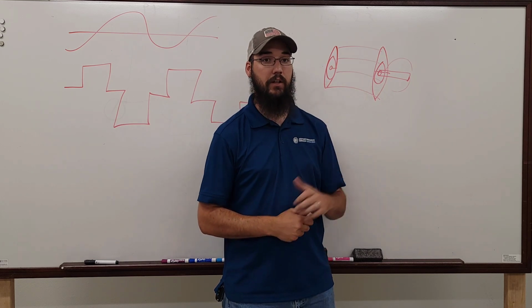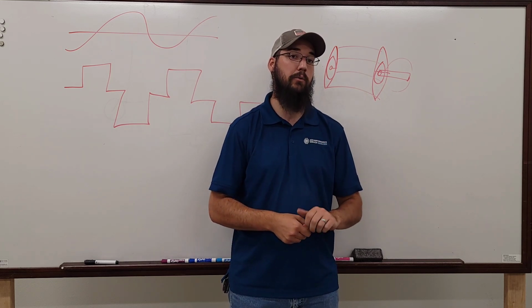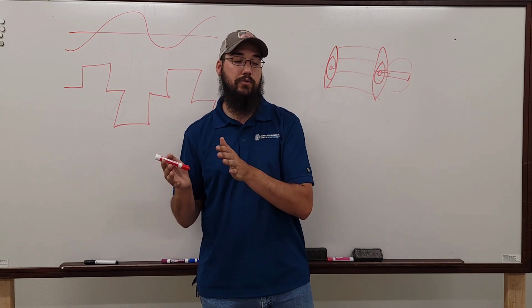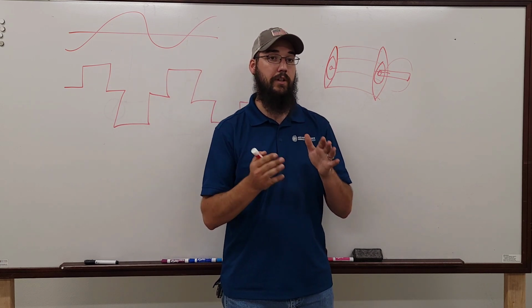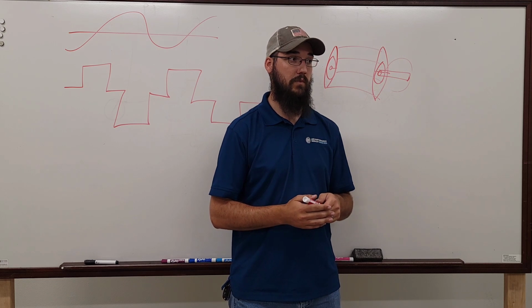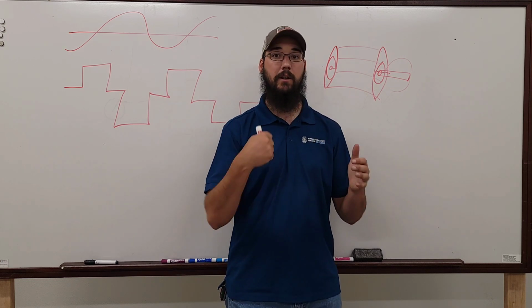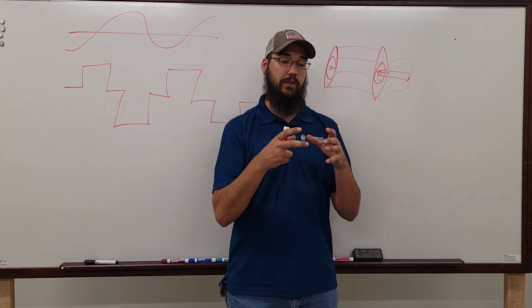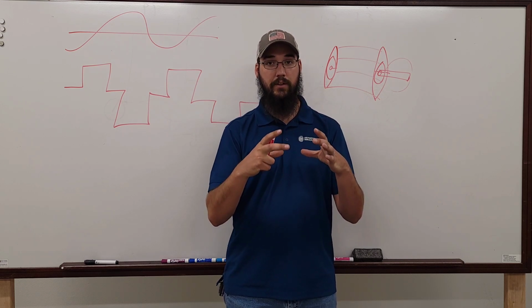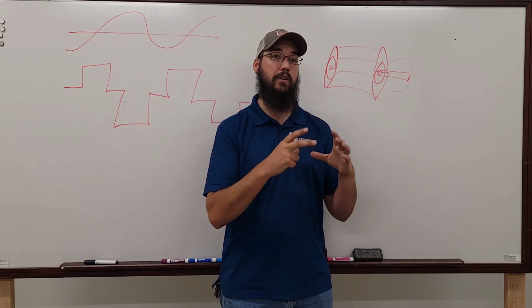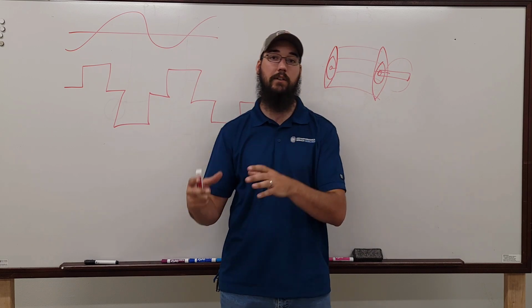Many of our VFDs that fail out in the field fail because the drives just couldn't get clean enough power. And over time, it's just getting pounded and pounded and pounded. Those have SCRs in them, silicon controlled rectifiers that convert that AC to a DC, right?